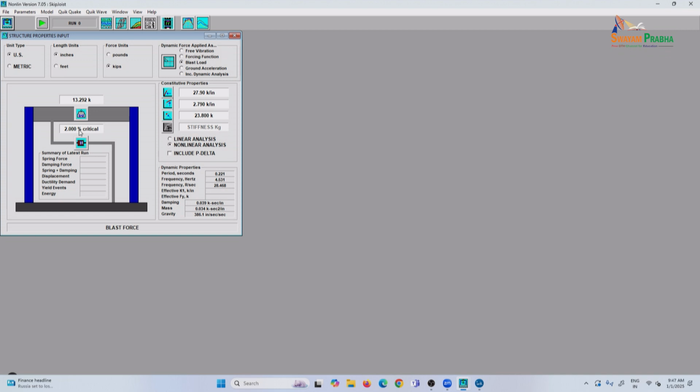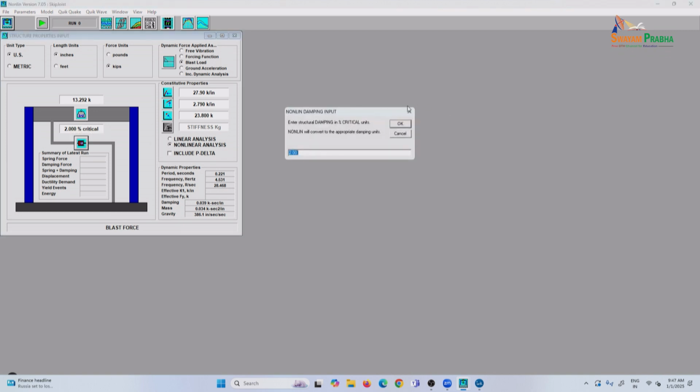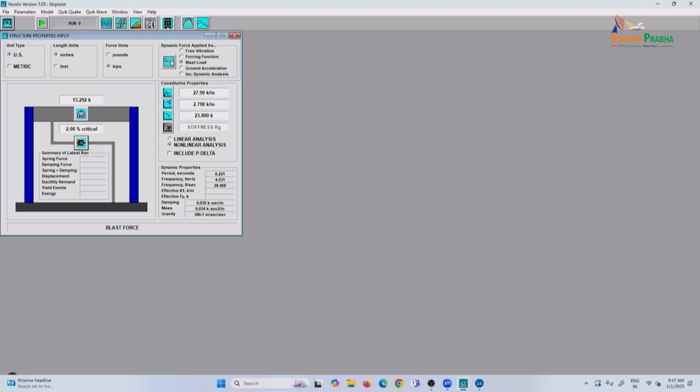So, especially in impulsive loading, there is a certain amount of dissipation. Whether it is important or not, we take the peak values for design purposes, but make sure you are giving it, otherwise you will not see any dissipation, it will just be elastic. So, when I input here, I am inputting as 2. So, that is one error I just wanted to point out that I had mentioned earlier.